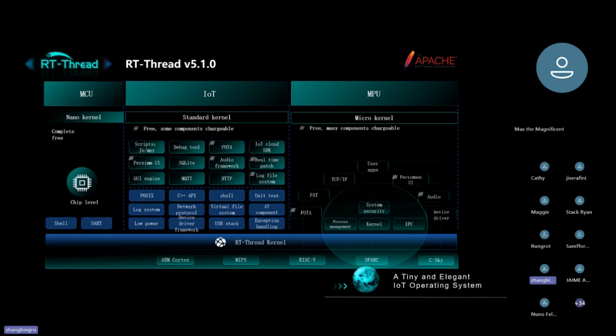Compared with Linux, RT Thread's kernel can be as small as 500K, which improves the startup speed and supports modular custom kernel functions. User state applications consist of two parts: system services provided by RT Thread, such as file system, network, UI support, etc. This allows some kernel components to run in user state, realize dynamic loading and restart, and improve system stability.